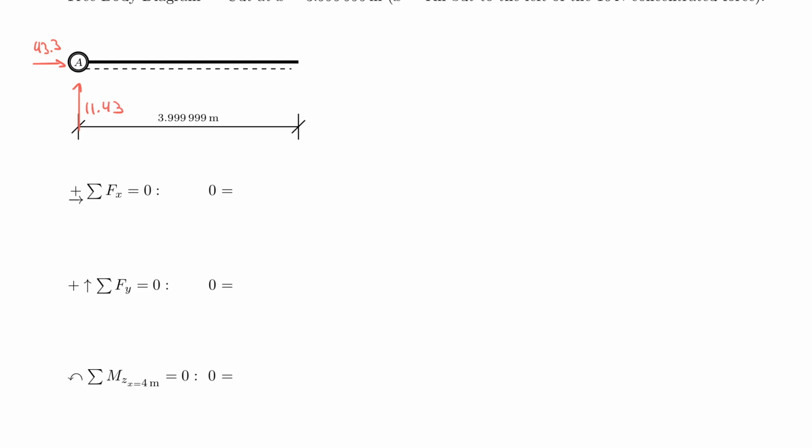are technically now external forces because I made a cut here. And the forces that I bring in are my moment, a shear force, and a normal force. Now, in which direction should I point them? I should point them according to my study card, and you of course have this in front of you. You have to trust me that I have this in front of me right now here as well. So my moment would go in this direction, my shear force would go in that direction, and my normal force goes in that direction. Why?